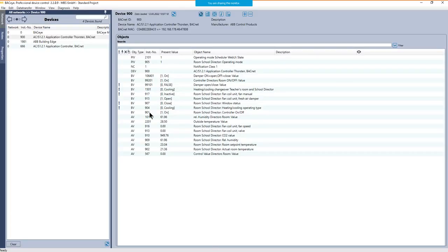So it's really simple to change outside temperature. I change again. 50 degrees I have adjusted. I refresh here. Almost 50 degrees. So very simple. Just an explanation: you see here BV, it's binary value. That is the ID number of the data point. You see the same in the ETS. I come back to this. And this is the present value here.